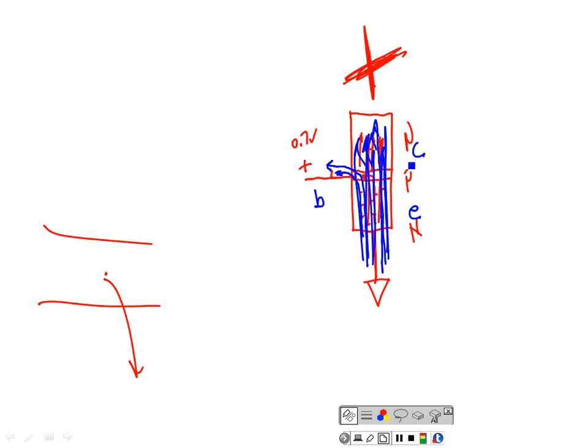Once we turn the valve on, I control the amount of current flow between the emitter and collector with base current. And it is directly proportional. It doesn't just mean they vary. If I double the base current, my emitter and collector current double. If I halve my base current, my emitter and collector current halve.